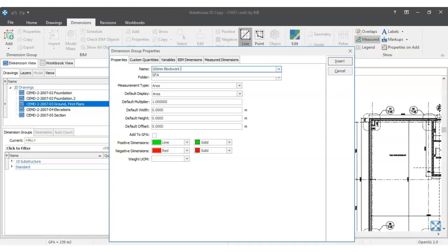And let's say external and ground floor. Okay. For the moment in the folder, we're going to put it in element 21, external walls. This is a new one, so I have to type it first, and I'm going to use the backslash or forward slash, whatever that one is on the left hand side beside your shift button, and I'm going to put it in a subgroup called ground floor, so I know what's ground and what's first.